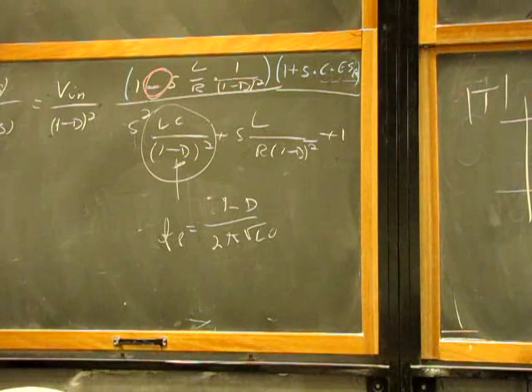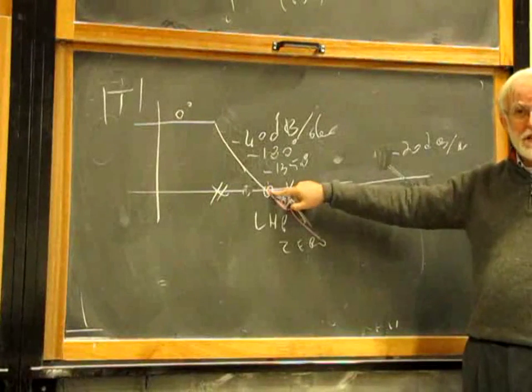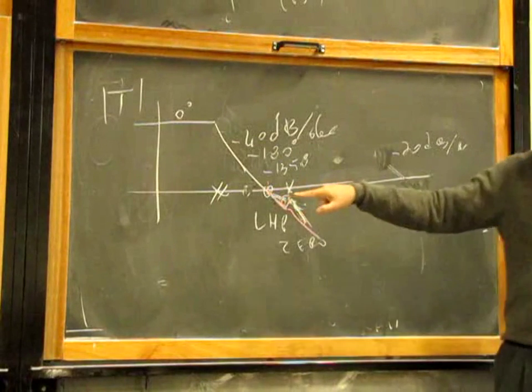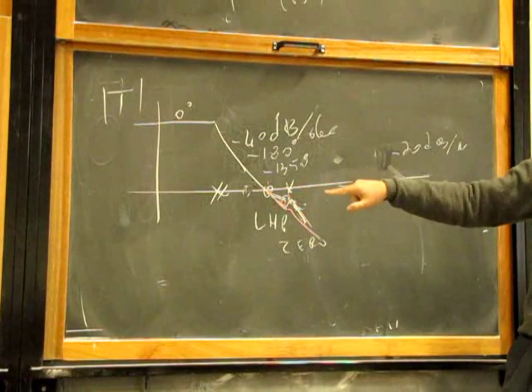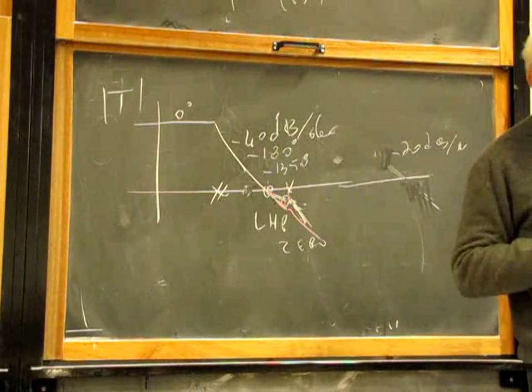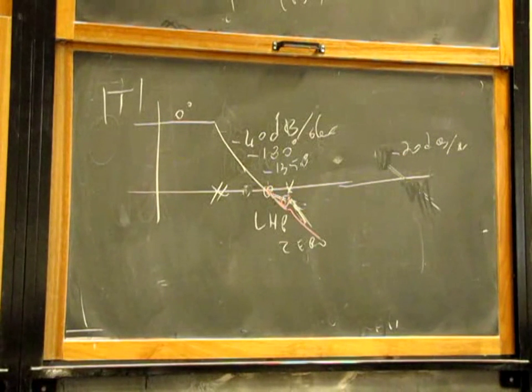Your left half plane 0, this 0 over here, that was stabilizing your system, moves above, past the crossover frequency, and your system becomes unstable. That is what happened to the company I told you about when I presented this problem. They didn't change any value. They changed just the manufacturer of the capacitor.